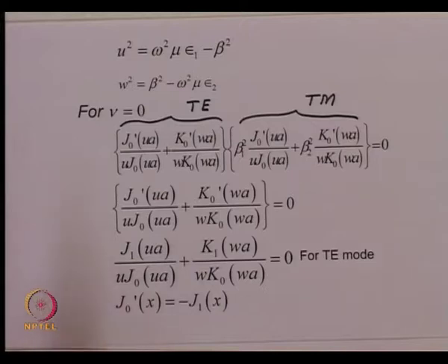For a given size of the optical fiber, one has multiple solutions. So now, for designating a mode, I have two quantities. One is the azimuthal index nu, which tells how many cycles of variation the field has in the azimuthal direction. And second, which solution of the equation is representing the mode.